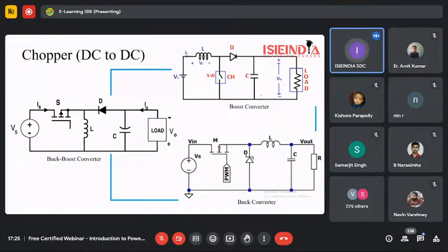Now we talk about the choppers. Basically, choppers are used for DC to DC conversion. So let's suppose here we have a boost converter. From the name you can say that whenever we want to increase the voltage level, like at the input we have 12 volt and we want 48 volt at the output, we will be using a boost converter.